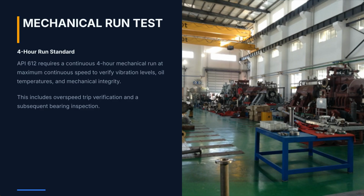We verify every vibration level and oil temperature. We even do an overspeed trip verification and a full bearing inspection afterward to make sure that there are zero hidden issues. It's a 4 hour gauntlet to prove the machine is ready for a decade of service.